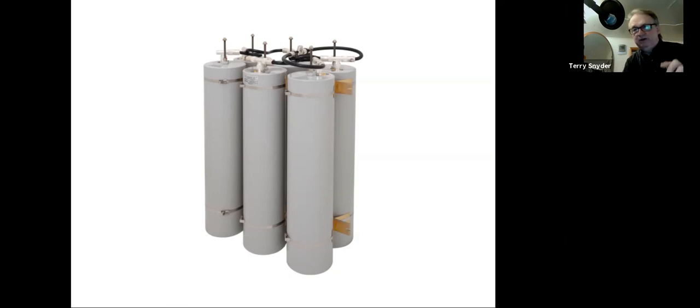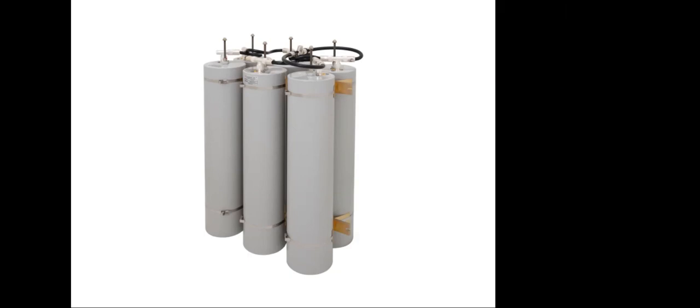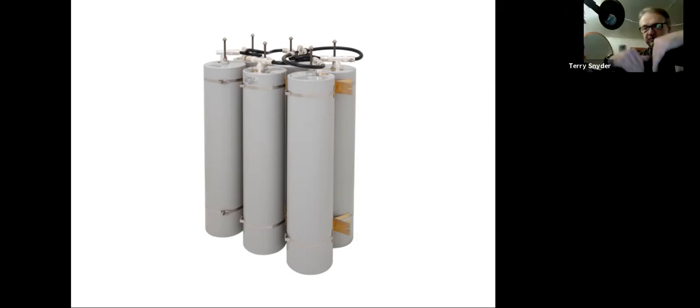Why three? Because you need to have that dip be extreme when it comes to the receiver. It's got to be an extreme dip, and in the transmitter, it's got to be an extreme peak, because you want the transmitter to go out into the antenna, but for the signal going to the receiver, you want to tune out that specific frequency that your transmitter's on.